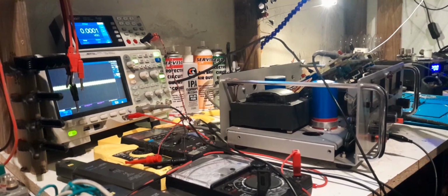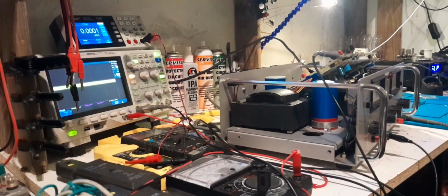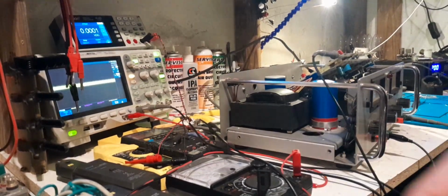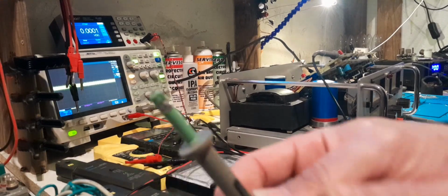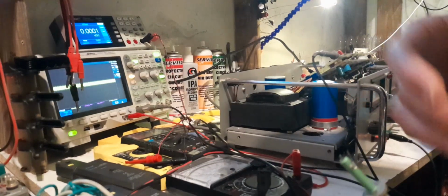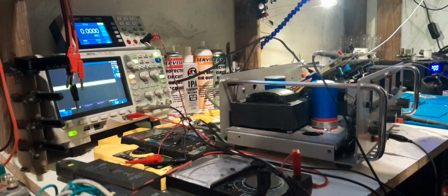But here's the thing. Sometimes, let me just grab this probe I've made. As I've shown you guys, I've made these probes where I've minimized tip capacitance and I've soldered a very small wire, so I can solder that directly across things. For example, if one end of a reference goes straight back to a power rail, like straight back to a capacitor from the power supply, the rectifiers and the transformer, in that case I'll be soldering the ground to the power supply rail and the tip to the cathode.